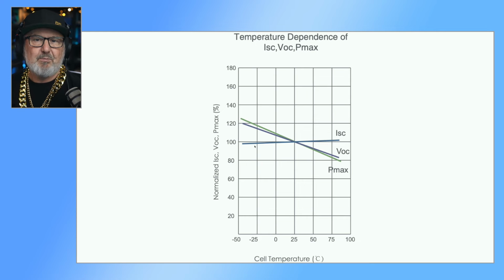So it's both potentially exceeding the voltage rating of the equipment, particularly the inverter's input voltage if it's too high. And also it's a safety issue. You may be trying to switch off the PV array at that moment and your switchgear can't even cope with that peak voltage for a short period of time. So we always talk about VOC max in our standards, never just at operating conditions. So it's the maximum that we're worried about.